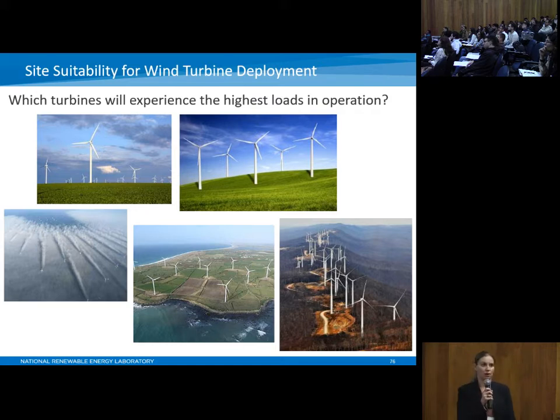But ridges are crazy weird in terms of creating speed-up effects and all sorts of updrafts and other types of flow conditions that might be harmful to the turbines. So if you're going to put turbines here, you can optimize them for energy capture, but you better be sure that they can withstand the loads at that site. Okay, any others?